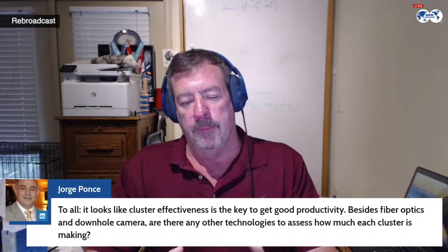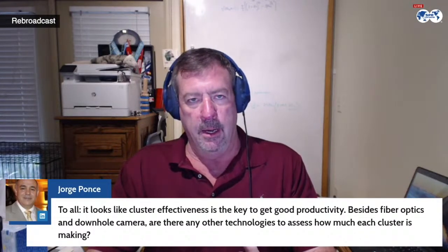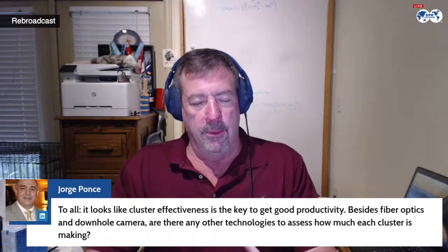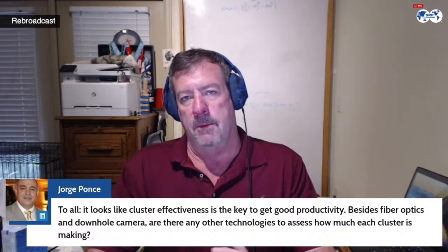And for those of you that have looked at some of the work DOE has done on the very complex initiation patterns near the wellbore, you'll kind of understand what I'm alluding to here. But because of that, where you have inflow into your horizontal well may not represent where that fluid originated. That fluid can come from somewhere else along the wellbore, migrate up through this complex fracture pattern around the wellbore